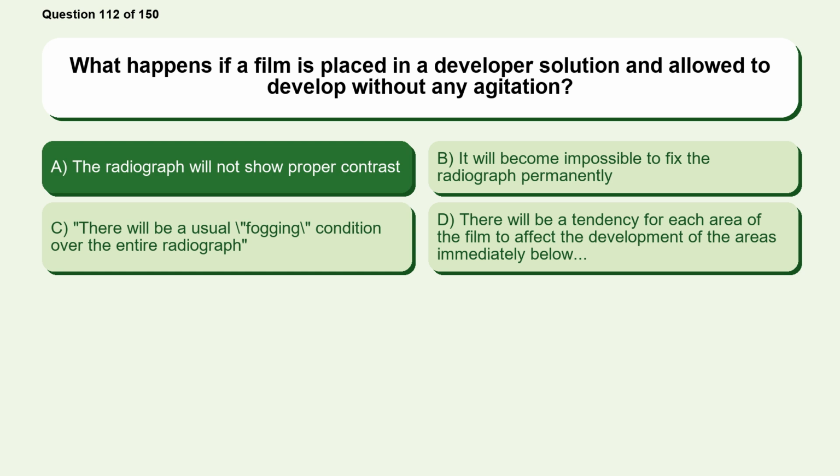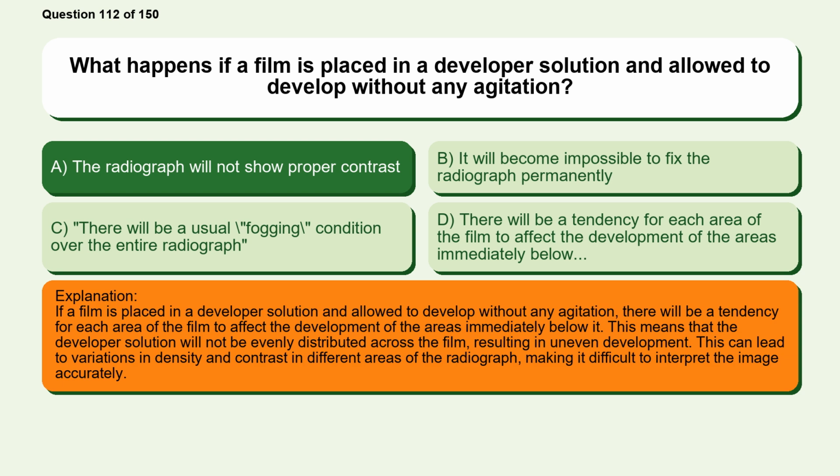The radiograph will not show proper contrast. If a film is placed in a developer solution and allowed to develop without any agitation, there will be a tendency for each area of the film to affect the development of the areas immediately below it.